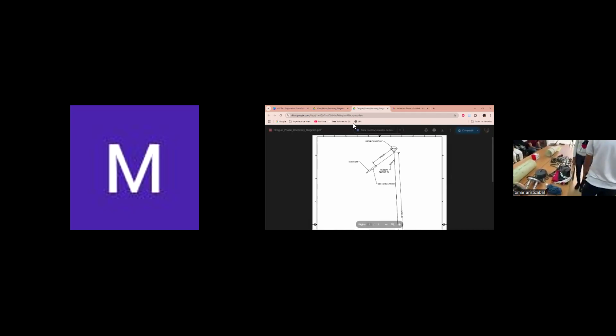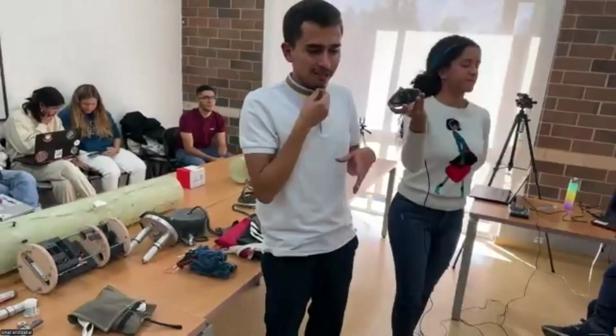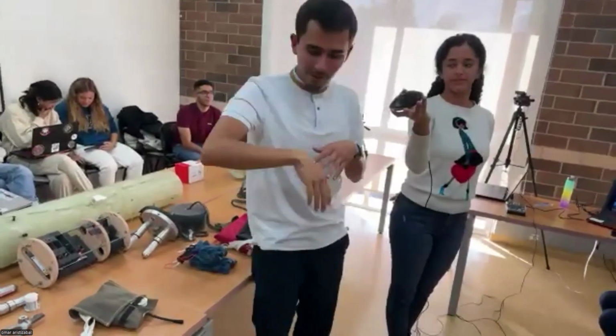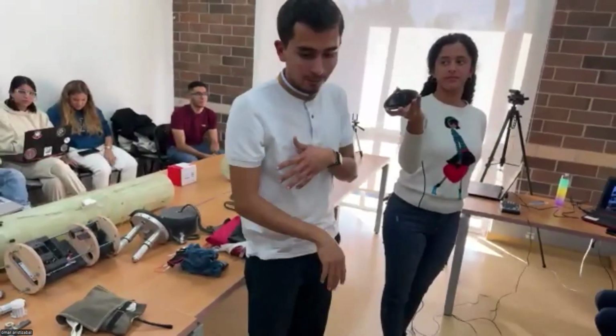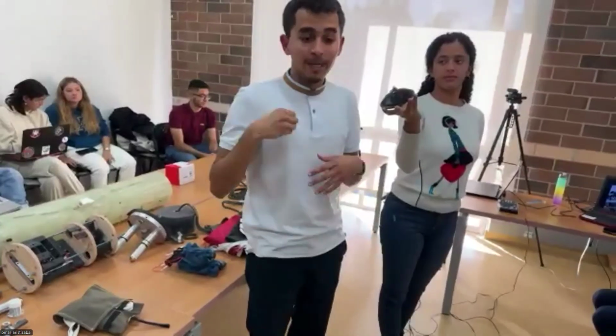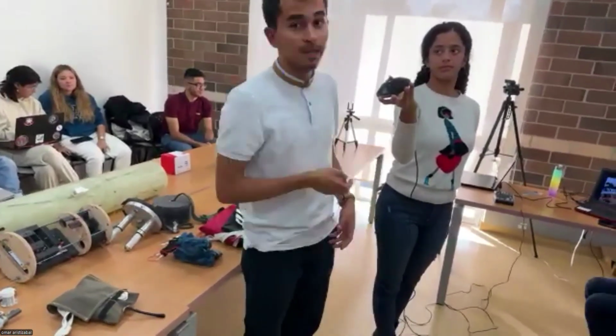We also made an assumption to define this length: I am ejecting my nose cone downwards, so we cannot allow the full length of this shock cord, once unfolded, to hit the engine section.